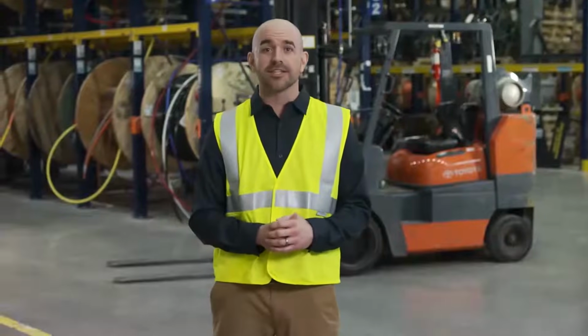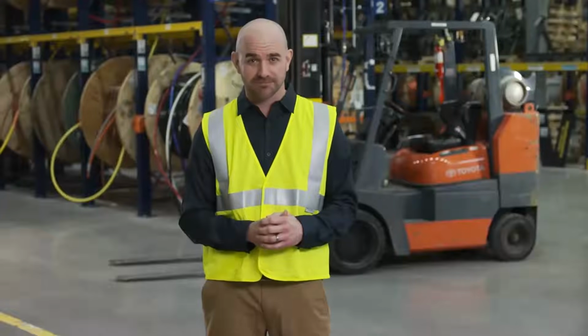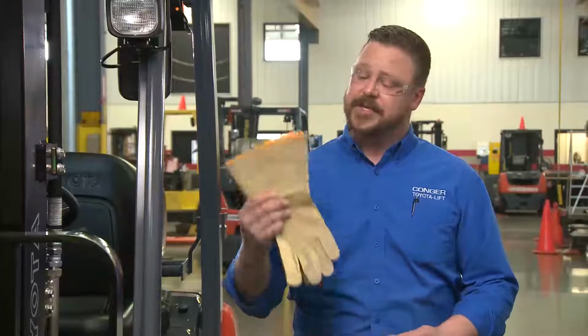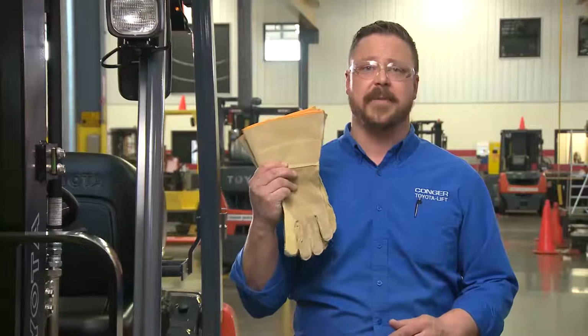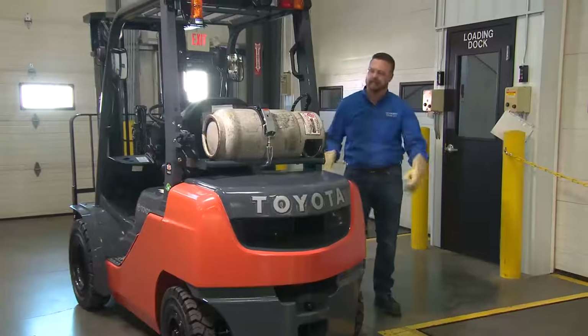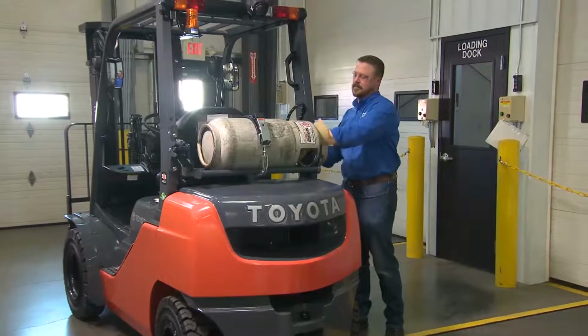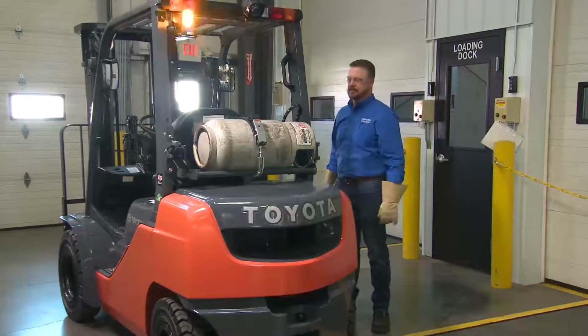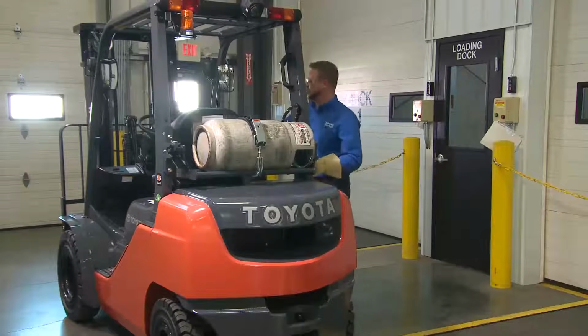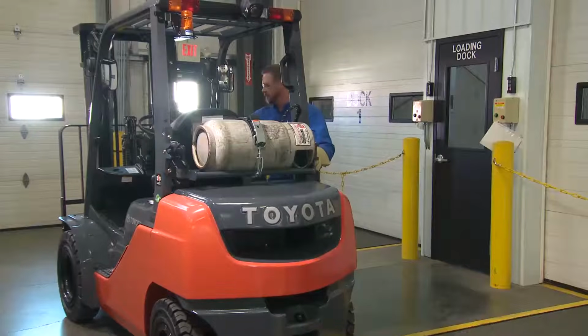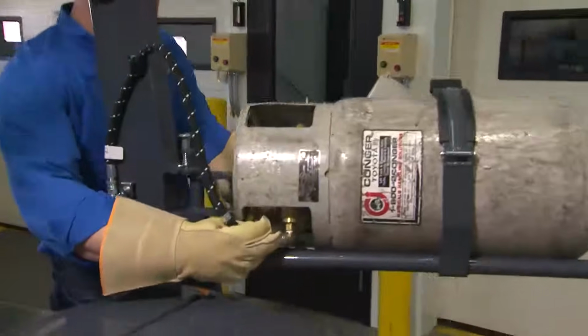Looks like we're ready to see an LPG cylinder swap in action. I always follow these steps when changing a cylinder. I have the unit parked with the engine running. I always make sure I have my protective gloves on so I can protect my hands from liquid propane freeze burns. Close the fuel line valve on the cylinder and let the engine run until it stops. This guarantees that the connection hose is empty of propane. Then shut off the ignition. I'm going to disconnect the hose and the holding straps.